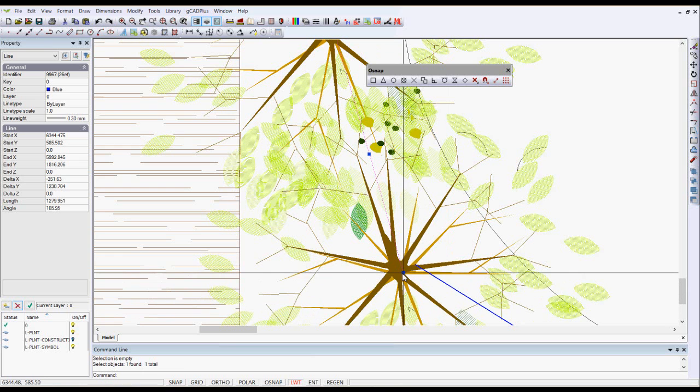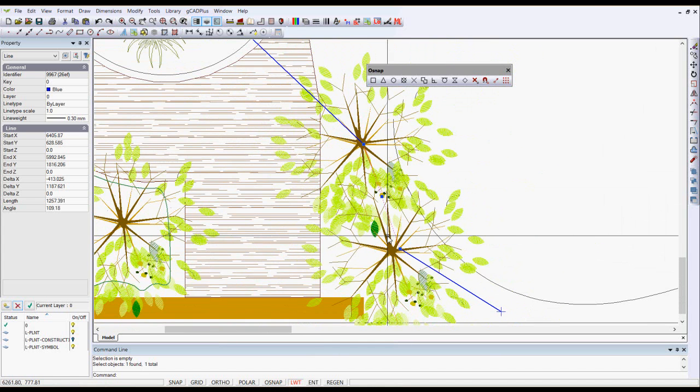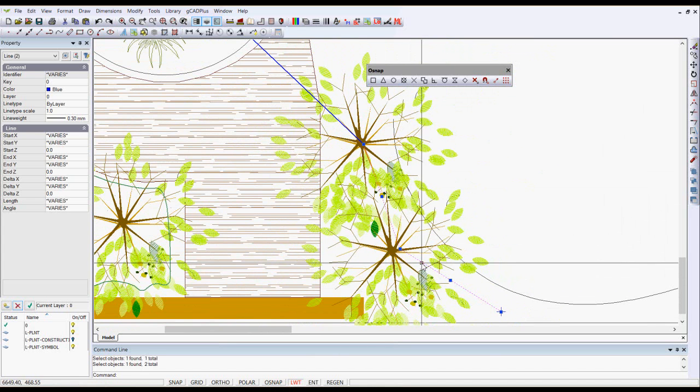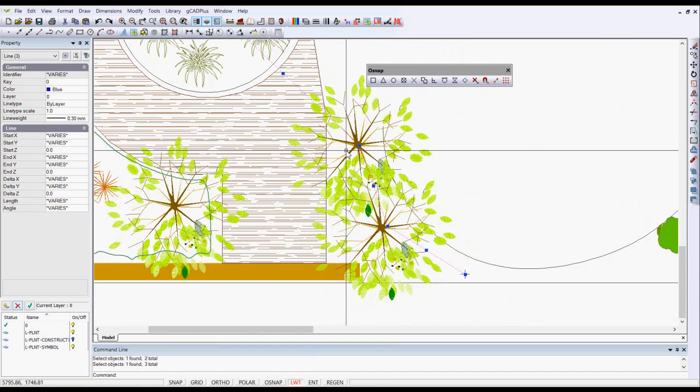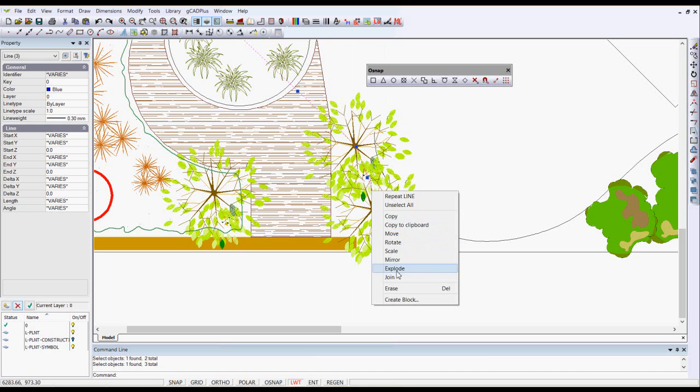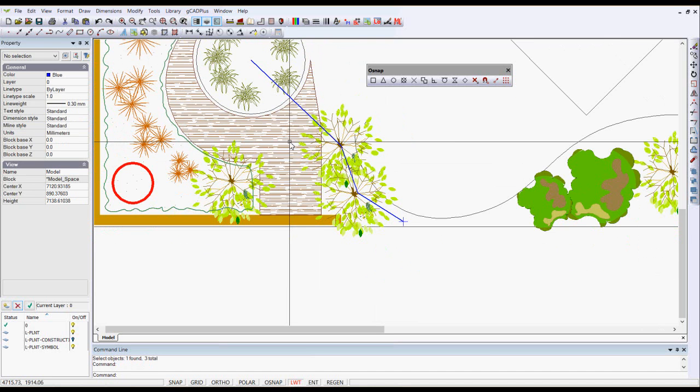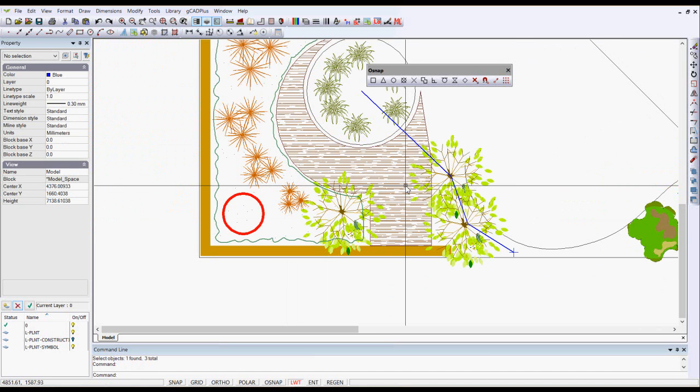If I now click onto find the end point of that line there, and then the end point of the adjacent line, can you see now the 2 lines have contiguous, same start and end points. So now they're selected and I can join them. So I hope you can see that entity snaps are pretty handy when you are editing a drawing.